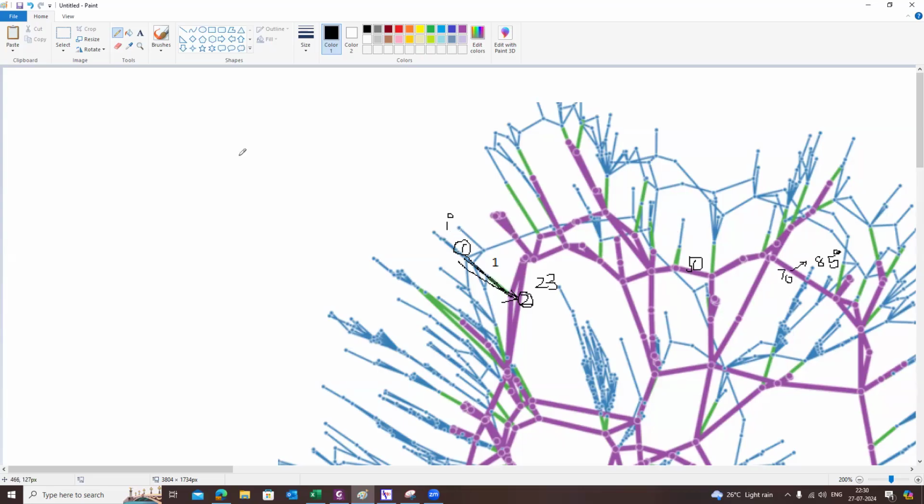If your system has only two buses, you can go up to 90 degrees. Suppose you have a radial system, with generation here and a load connected here. If your system is only like this, then the angular difference can go up to 90 degrees between these two buses. But unfortunately, our system is not like this.